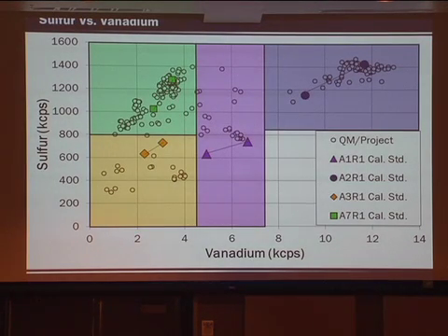That may not make a lot of sense, but hopefully this will. Every asphalt, like we said, has sulfur and vanadium included in it. The little white circles here are 250 asphalt samples that we've tested using the XRF. Number one, you can see some interesting trends: it doesn't appear that there are asphalts that tend to have low sulfur and high vanadium. You get this roughly 45 degree aspect. Number two, this graph is a little cluttered, but you can start to see some delineations here.